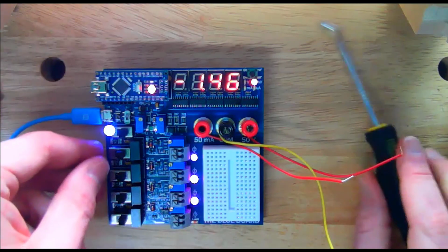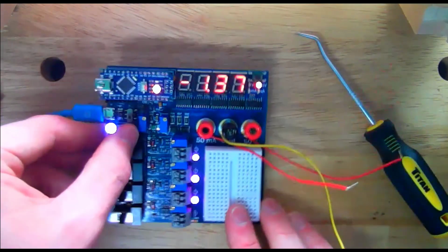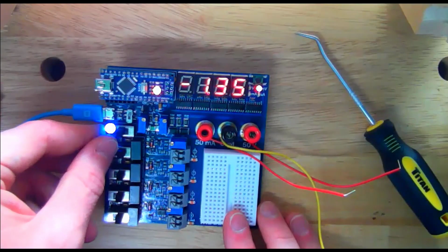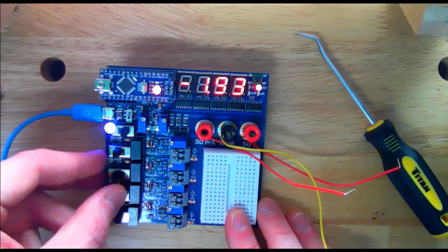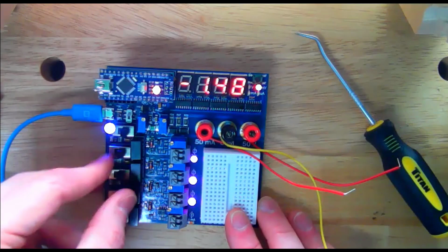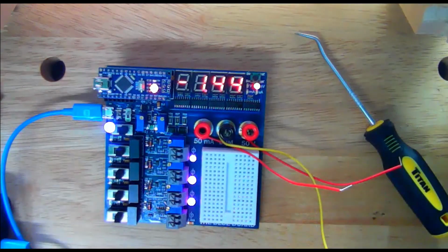We can turn all the supplies off by flipping the top switch. That turns them all off. We can turn them individually on and off by switching their own switch, so you can see those lights come on. It should be noted, a supply that is turned off is not the same as a 0-volt supply. Turning the supply off is not the same as setting it to 0. It's just not powered, not energized. You don't really know what it's doing. So you still need to disconnect it from your circuit if you're trying to disconnect it.